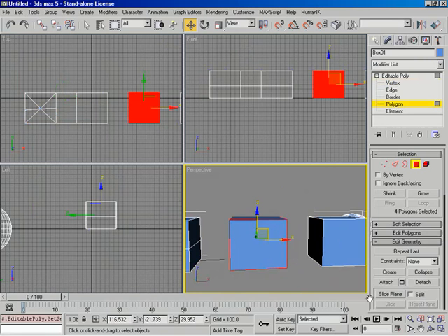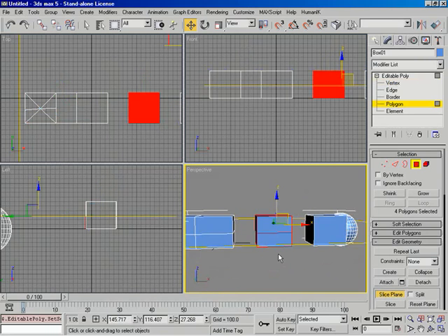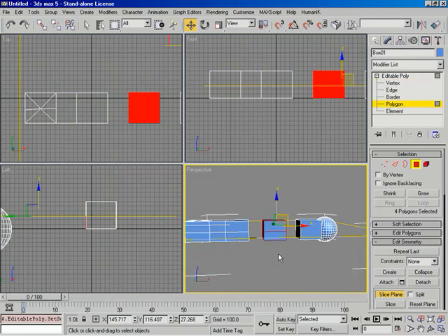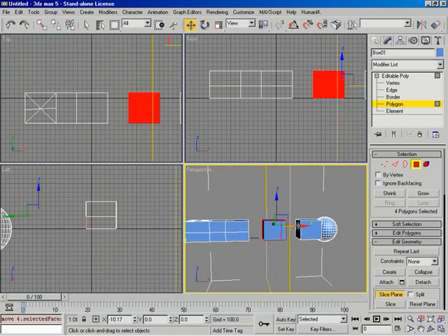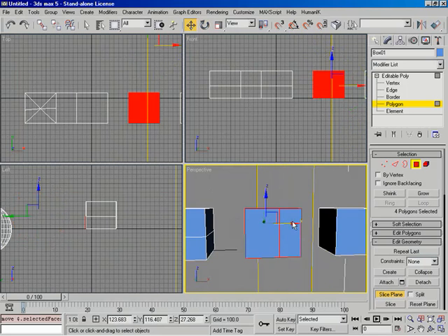Oh, wow. So let's go ahead and turn my slice plane back on. Let's go ahead and demonstrate the fact that we can scale this. We not only move it, we can scale it and we can rotate it. I'm going to turn on angle snaps, grab my rotate tool, and just rotate this guy quickly, 90 degrees. And now let's go ahead and turn that off, and then we'll just move it back over, and you can see there comes our interactive edges. All right, it's about right there.